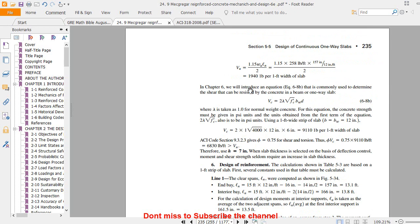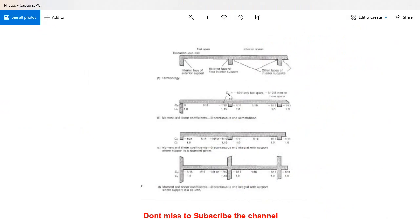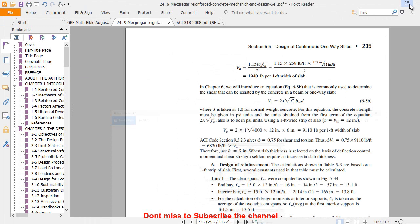You just calculate your Vu, which is 15% more: 1.15 times wLn divided by 2. Here you see the coefficient for shear is 1.0, but for here it is 1.15, so that's why 1.15 wLn divided by 2. This is the maximum coefficient. So our shear is 1940 pounds per 1 foot width of slab.